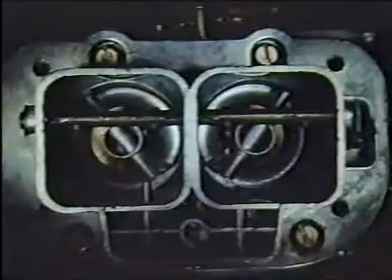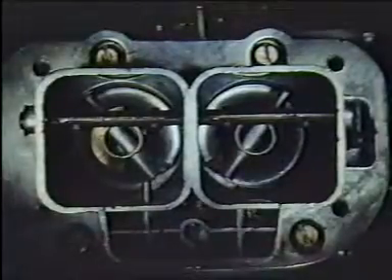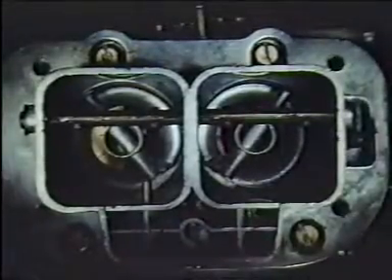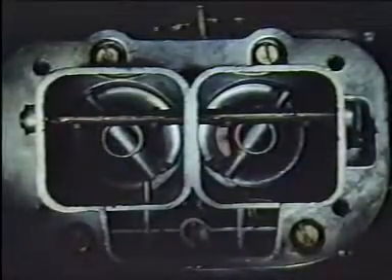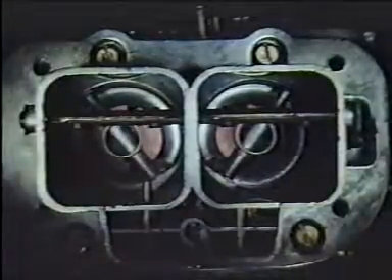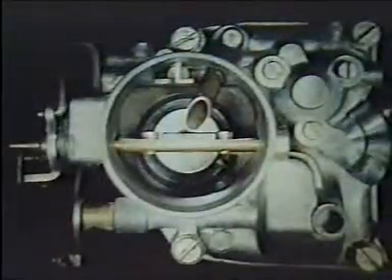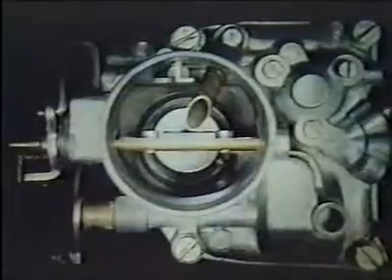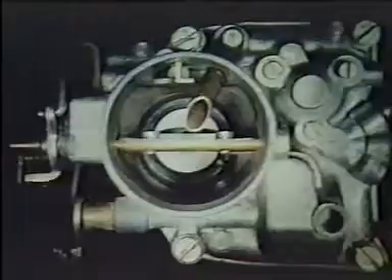It consists of two carburetors of different diameters side by side in the same casting. At lower revolutions, the needs of the engine are met by the smaller carburetor. At higher revolutions, the larger diameter carburetor comes into operation, greatly increasing the flow of mixture into the engine and improving its performance. The task is always the same. It is simply to deliver the right mixture of fuel and air to the engine at precisely the right moment.